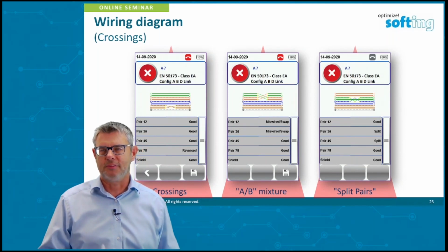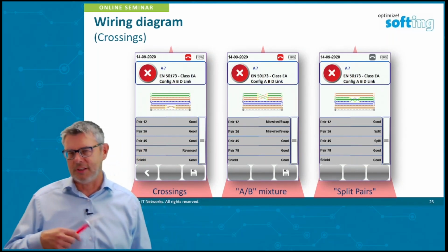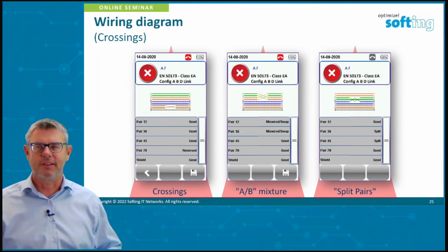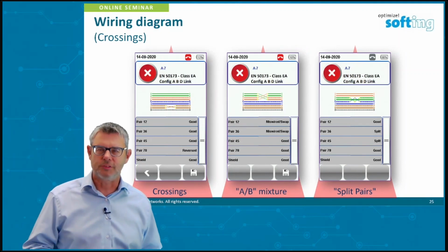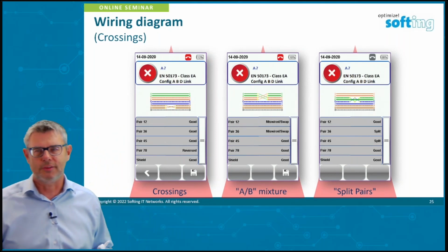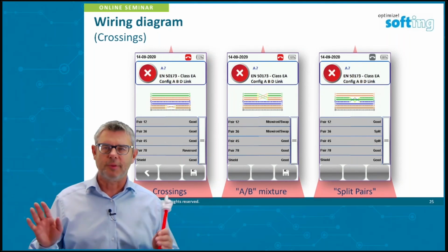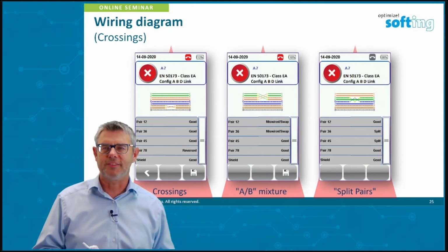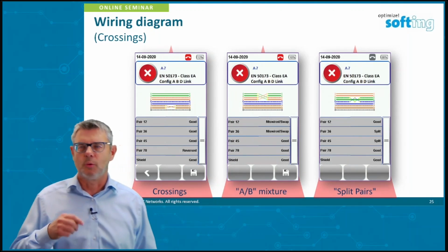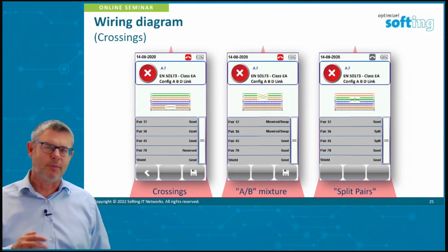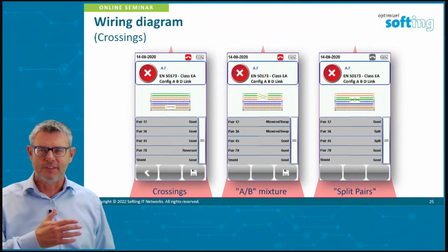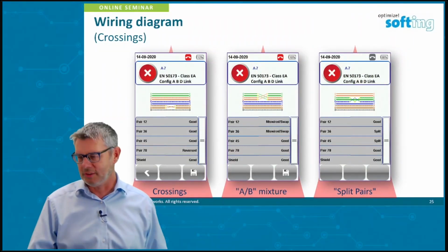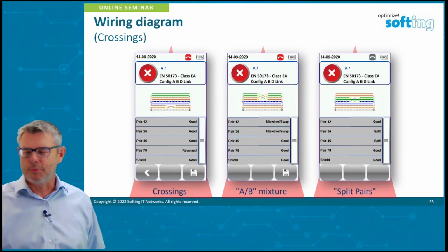That's a very tough error on the RF side, and we will see later when we talk about the next error. This is one of the results. Next will definitely fail on this. Okay, this is a typical screen for basic wire map errors. Honestly, wire map errors make up about 80 to 90% of all errors you have in the field, because this is the human factor working on this. So let's move on to the next parameter.